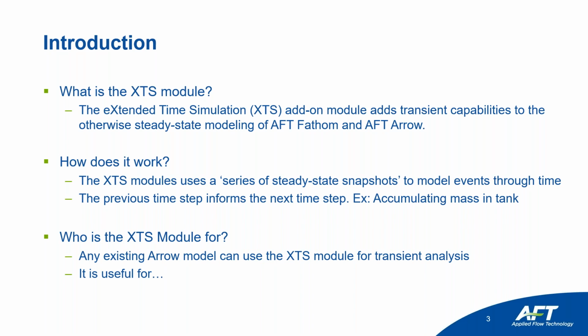So it's going to be useful for all sorts of different things. Again, one that I've already mentioned is seeing how you can accumulate mass in a tank, where very gradual changes in the mass downstream or upstream aren't going to create significant pressure waves that, in this case, the XTS module will not track. Because it's assuming that at each time step it's reaching a new steady state, it's unable to track things like pressure waves that would transmit through a system, for example, in a water hammer event or in a relief valve event, or any of those what we call rapid transients.